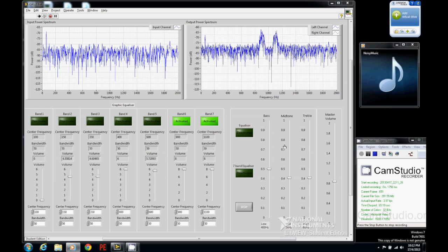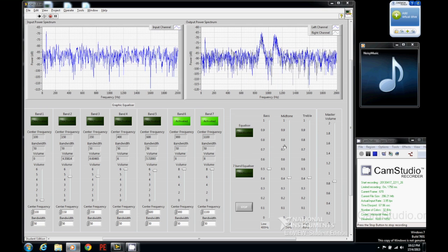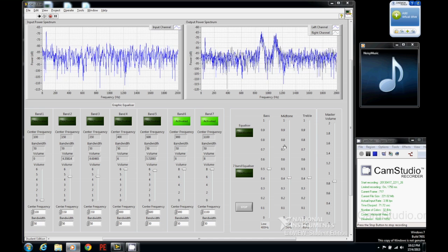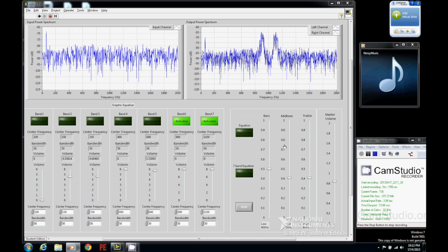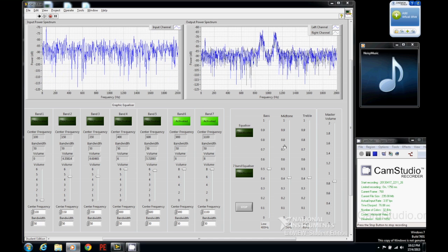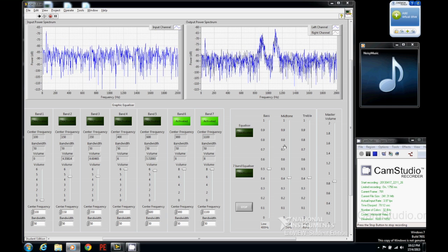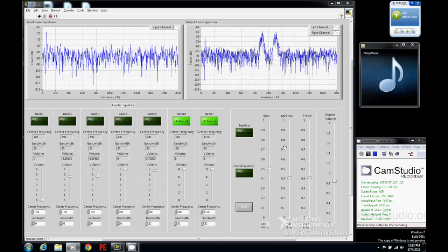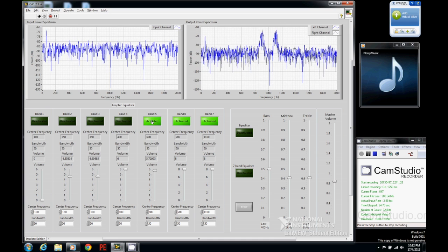These produce a better result as the 1 kHz tones is now perceptually less significant to our human ears. These two maskers are able to compensate with each other since the frequency content in these two bands are not consistent. So this is the best result we can achieve, and we apply the same approach for the rest of the tonal noise.